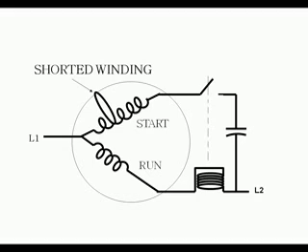If you have a short circuit to ground, there should be no continuity from a winding to ground. Mega ohm meters can be used to detect small, high resistance paths to ground. In damp conditions, dirty motors may have a resistance reading from windings to ground. If refrigerant oil is dirty, hermetic compressors may have resistance readings from a winding to ground. Either way, the motor should be replaced. The ideal condition: no continuity from a winding to ground.